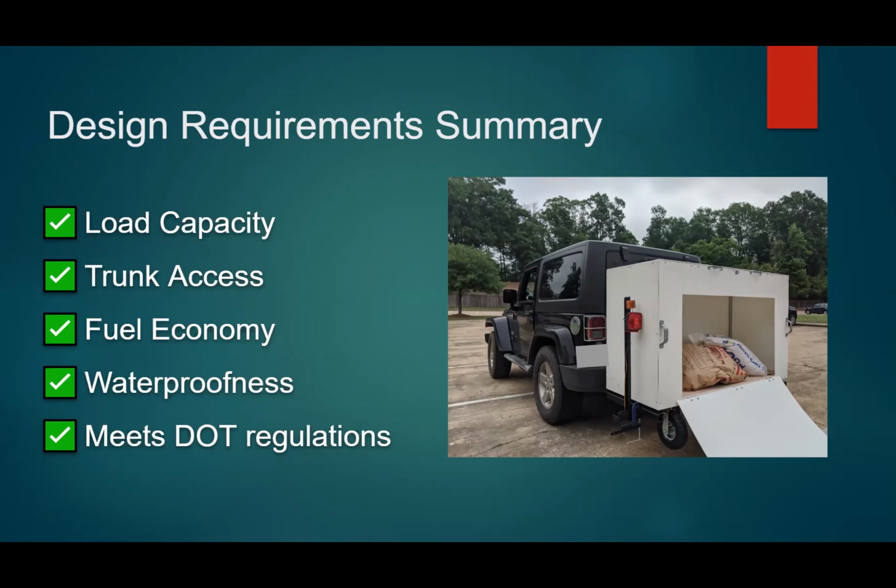Okay. We didn't specifically test that. What I did do and didn't show on here was that the analyses that I showed were for a 250-pound load, which actually includes the weight of the enclosure plus more than the 150-pound capacity we were looking for. But previously, I have done a calculation with even over 500 pounds of that same load, which doesn't exactly compensate for that torsional factor, but it gives me confidence that it would be okay. But that is a good suggestion. Thank you for that. We may include something like that in our report. No, yeah, you did a good job. Thank you.